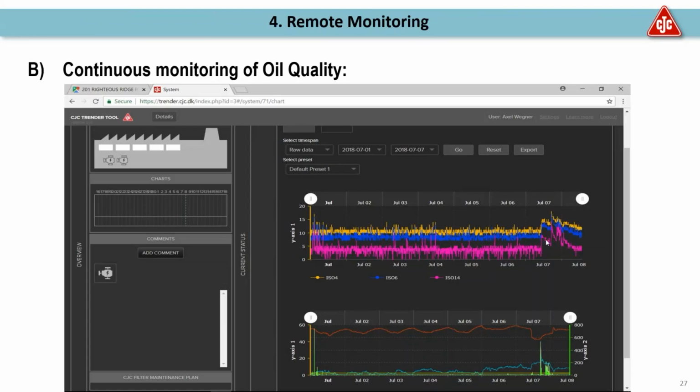And then you have a little bump all of a sudden, and also here down the green line in the lower graphic, which is the raw particles larger than 40 micron. Now, what happened here is simply adding some oil. Another thing that you can easily see here is startup and shutdown of your turbines or other equipment. Everything will now leave a fingerprint.